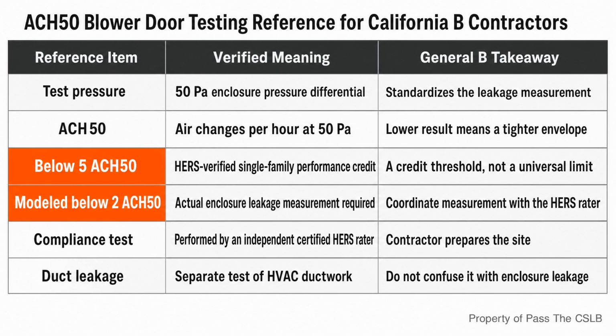Spray polyurethane foam can serve as insulation and air sealing material in an appropriate assembly, but its installation introduces hazards that must not be treated like ordinary dust. The chemical components can expose workers to isocyanates, which can irritate the respiratory system and can cause sensitization. A sensitized worker may react to later exposure. The fact that the finished foam becomes solid does not make the spraying process harmless.